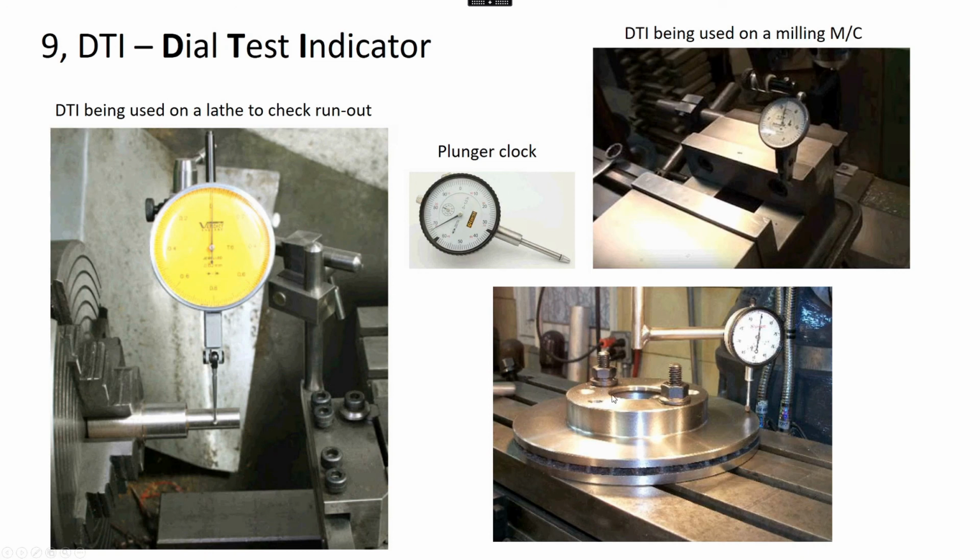If this smaller hole is the diameter that locates the disk, you clock up this diameter instead and use that as datum B. But the important thing is the first face that you clock up is the datum A basically. And that's how you set the part up on the machine.